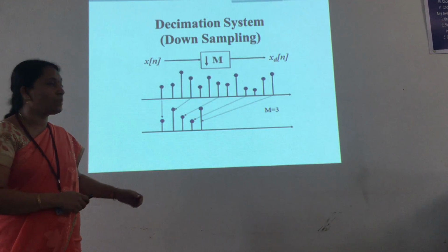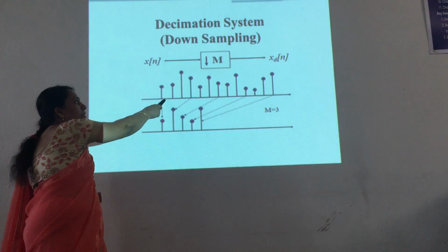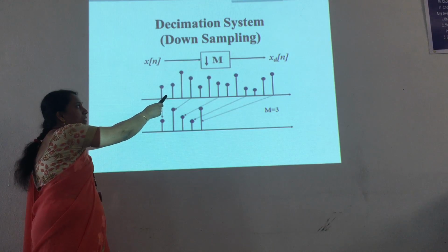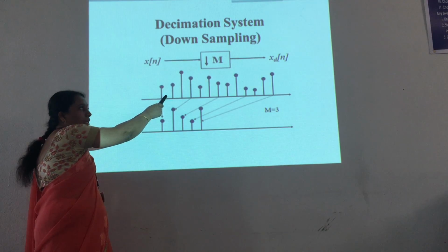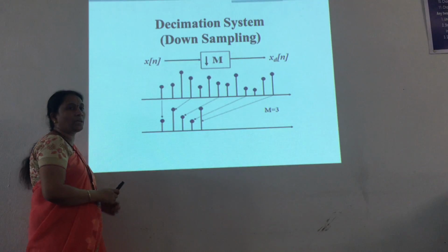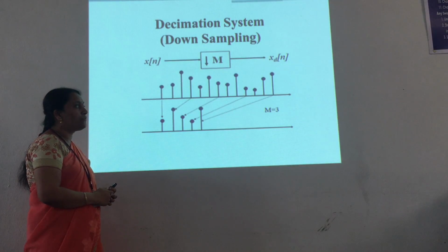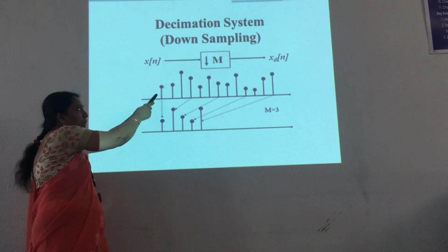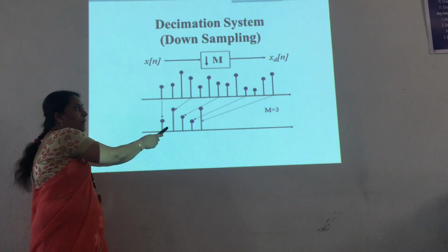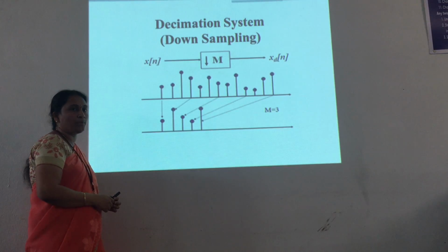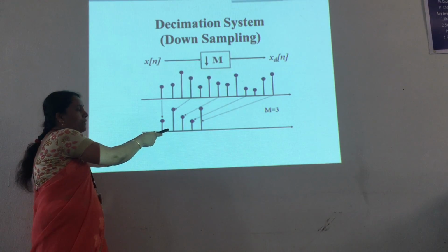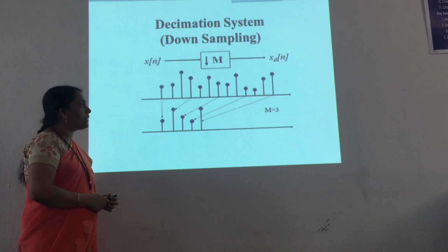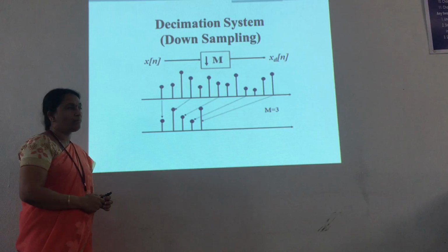See, this is the figure. This figure represents the original input signal. So here this figure contains different samples. This figure contains a total of 30 samples. These 30 samples we can decrease using a decimation factor of 3. So if the decimation factor is 3, we are decreasing the number of samples in the input sequence. Thereby the output sequence contains only 5 samples. So we can decrease the sampling rate. In this figure, the number of samples is decreased, which means the sampling rate of the input sequence is decreased.